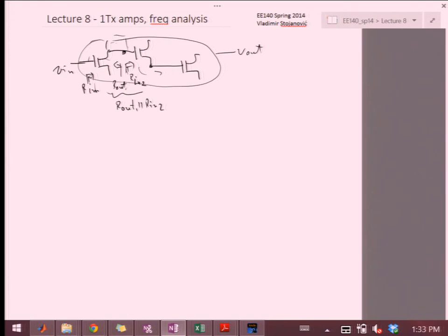But inevitably, it is true, and even though MOS is an inferior device, some of the calculations are easier with MOS because you can do this explicit isolation between stages. You don't have to worry so much about what's down the emitter path, right?